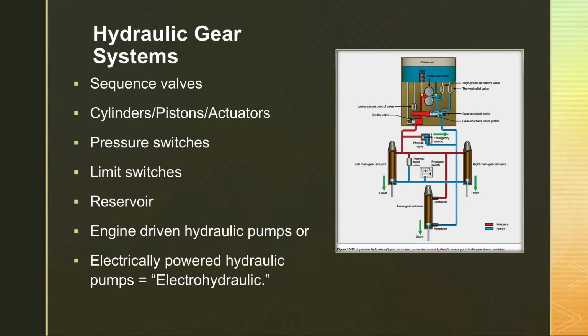Okay, hydraulic gear systems are generally going to be a lot more complex. Electrical gear systems are heavy. The gear motor's heavy. You've got to have definitely some battery power to help out with it. Hydraulic gear systems can go farther. They can provide a lot more power, and for a lot longer period of time, basically, before you deplete your electrical reserves. So you get higher pressures from them. They're a lot more complex, with a lot more chances for things to go wrong.